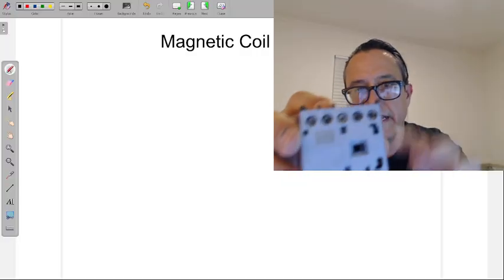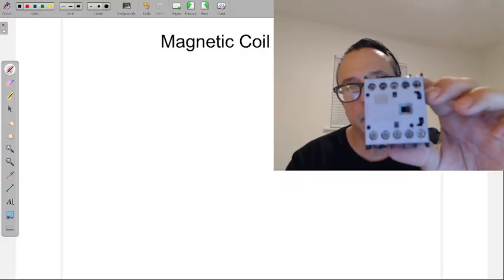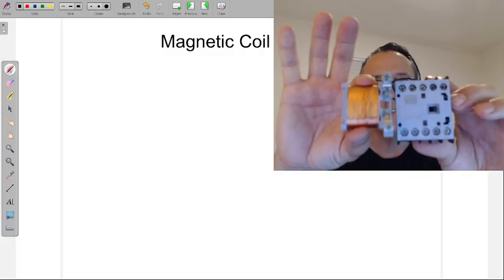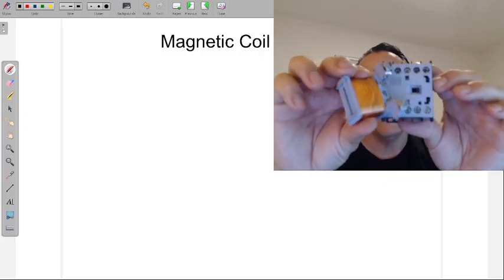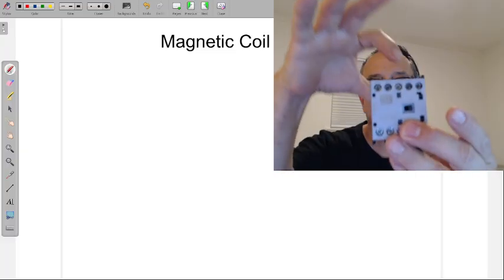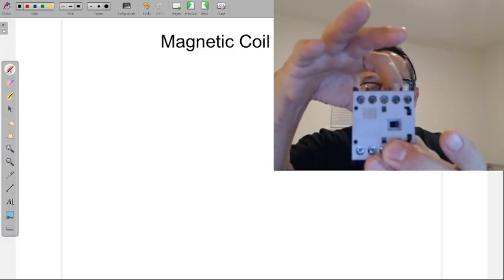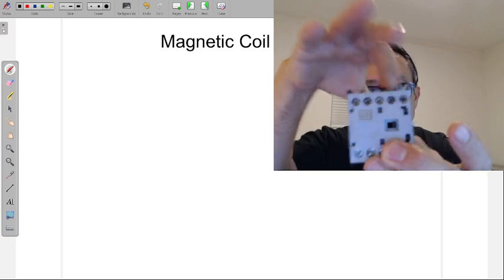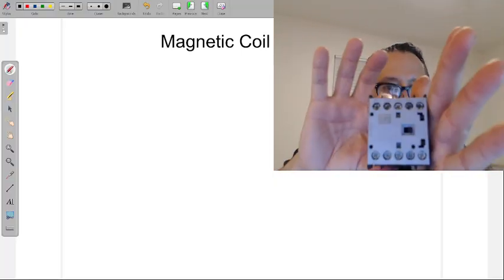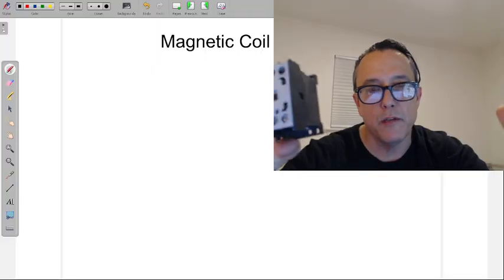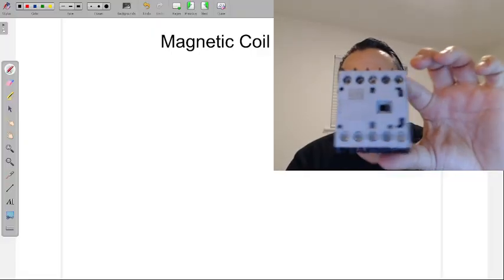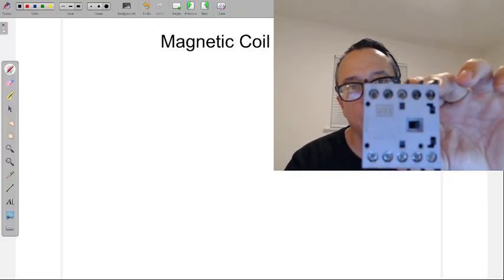This contactor right here, unlike the one that you are using, 120 volt style, in the in-person labs, simply has the coil sideways. Sometimes they have these facing up, where you find A1 and A2 on the top of the contactor. In fact, top of the contactor, A1, A2, is for AC voltage in Allen Bradley world. Now, are you always going to be using Allen Bradley? No. So just find A1 and A2 whenever you're dealing with a contactor. But Allen Bradley does have that one universal thing.